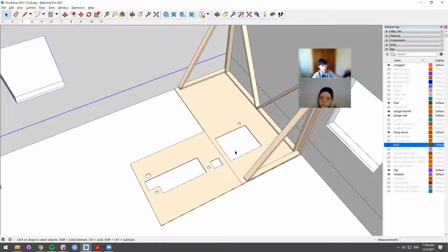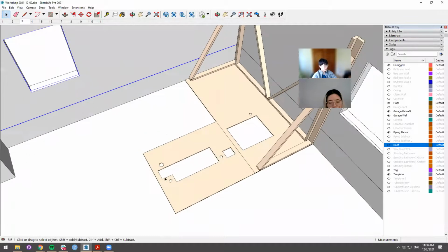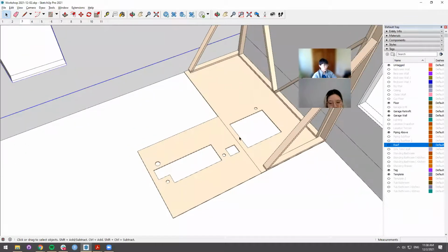So before you've done anything, of course, you do need to roughly know where the lateral sewer is. But the idea here would be to sketch out exactly where these penetrations will be. And then you can remove this template and actually start to saw cut the concrete.